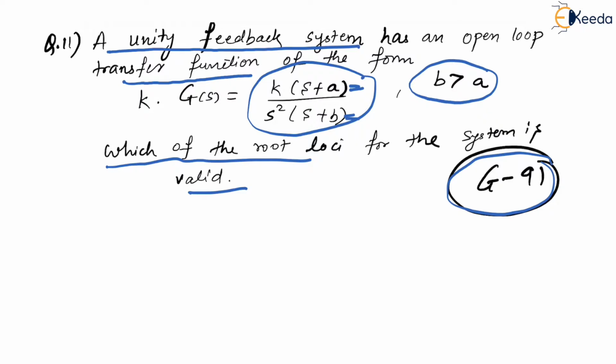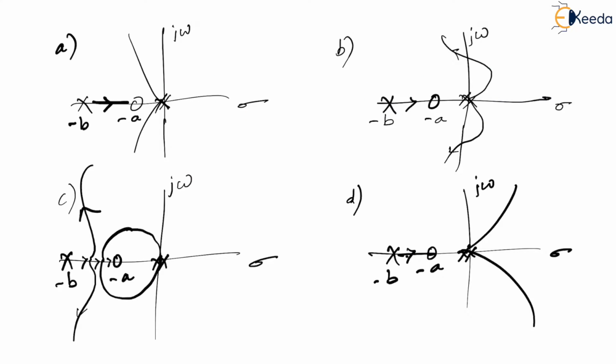Now, next thing, if you just observe, you have got these two poles at origin. And you have got this one pole here, and you have got a zero for that pole, which means that this pole has to terminate at some zero. Is my pole terminating to a? Yes, terminating here. Is my pole terminating to this zero? Yes, it is terminating. Is my pole terminating to this zero? We can't understand actually. This definitely is not the answer. Why? Because this is going here, but then there are some poles coming here also traversing here. Definitely this is not the answer.